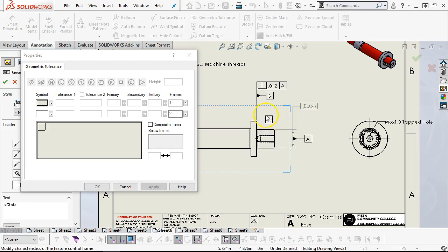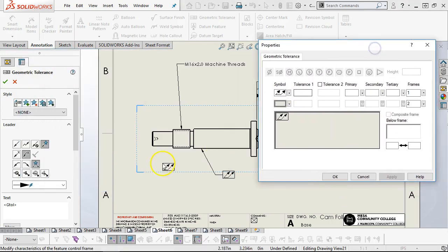The thing with the runout is that it's at a cross section where the total indicator runout is across the whole surface, so measuring both concentricity and its relation to the datums. So if we were to put a value, and actually I think since this is adding them pretty easily, I'll go ahead.